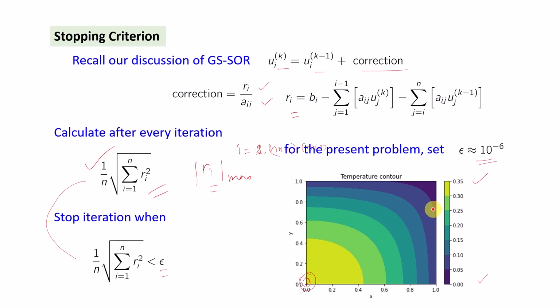toward this T infinity. If it is on the lower side, then you will get more of a gradual change. You will see that it will go toward isothermalization, meaning that the temperature gradients inside will be smaller if your Bo number is small enough. Those who have studied heat transfer call that lumped condition. But anyway, you will reach this solution if you implement it.